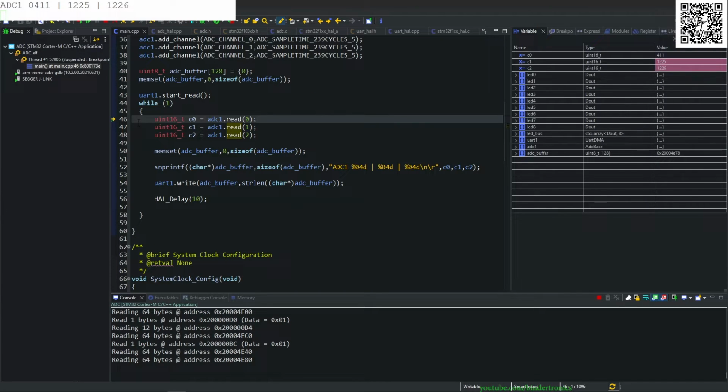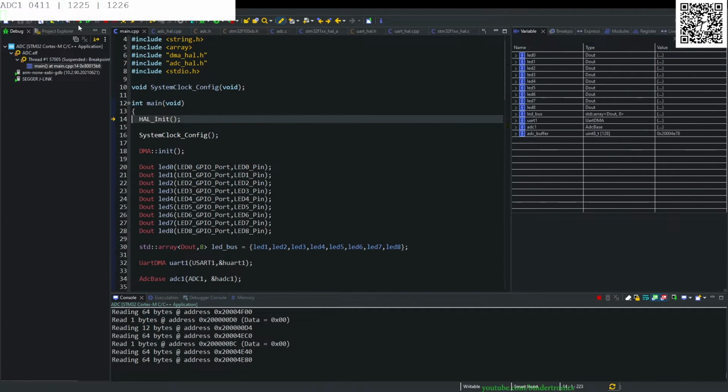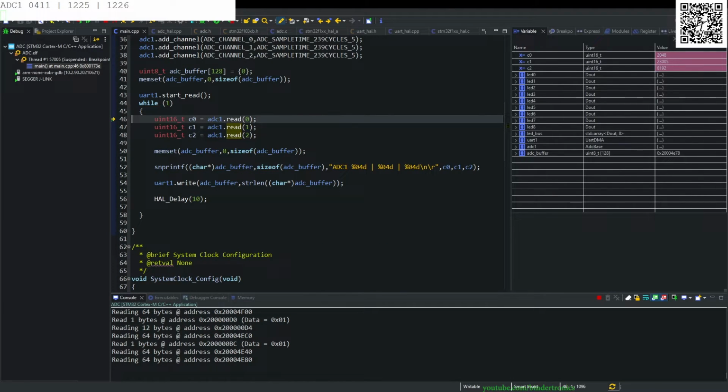Okay, so for interest's sake in debugging, if you watch the value up there on the left hand side, and I restart the chip and click resume, now I've got a breakpoint here before I do the readings. If you run it once, you can see all three have different values. If I run it a second time, values don't exactly match, but they're within range. And then when you start running it repeatedly, the two outer values turn into the same value, which is not correct. So I'm trying to figure out the why on that. I'll be back when I've got an answer.